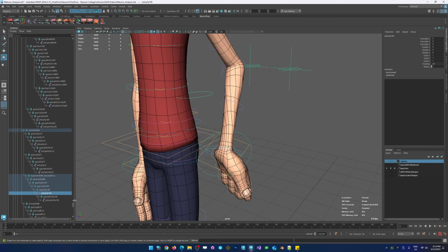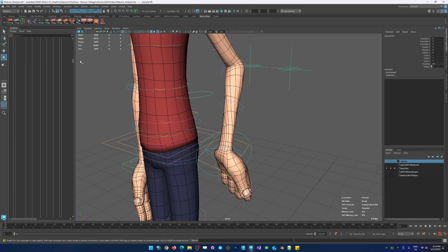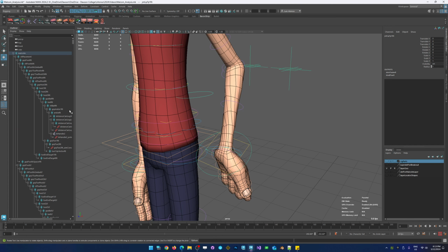All of those things add up to lots of extra little nodes, which means there are thousands of objects here, and you have blends between multiple setups. It's painful to fix things like this. If something goes wrong, this is really difficult to fix. So I'm not calling out the Malcolm rig in particular. There are a lot of other rigs that do exactly this, and I would say this is very much a classic approach in Maya.